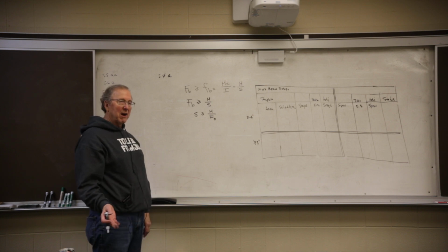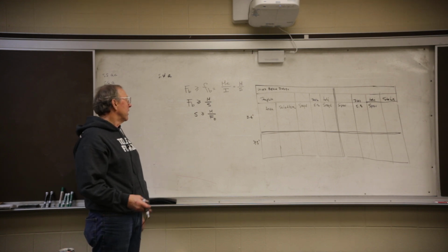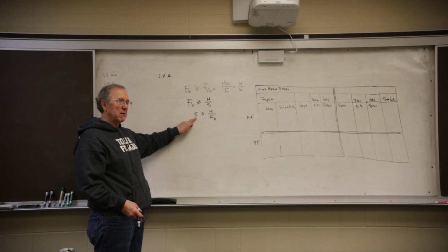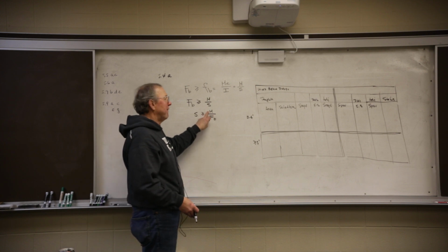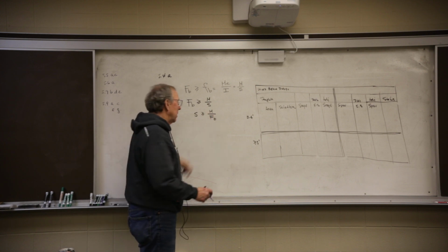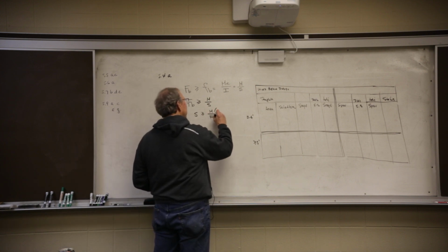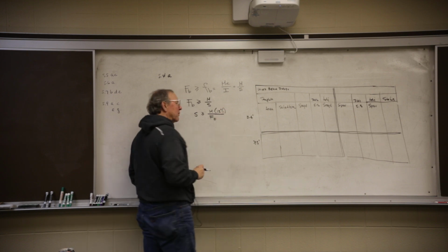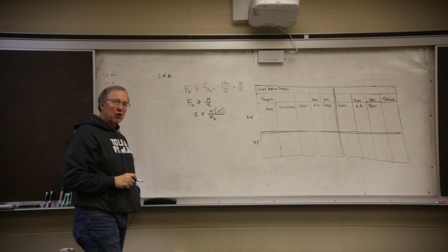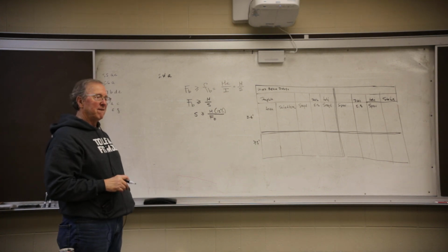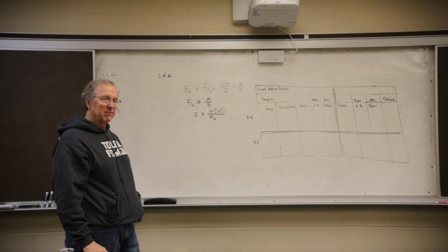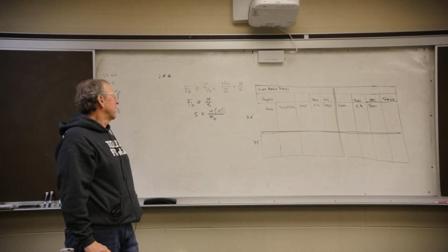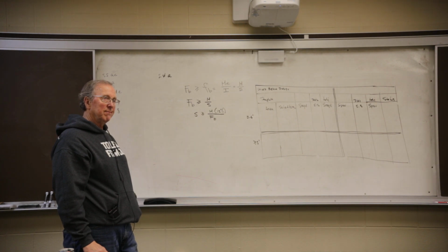Okay, one thing I want you to do when we do this: inches cubed, pounds per square inch, foot pounds. If your moment is in foot pounds, I need you to take this and multiply it by 12 inches per foot to turn it to inch pounds. A very, very, very common mistake on tests. Very common. So I would just change the equation so I don't make the mistake.